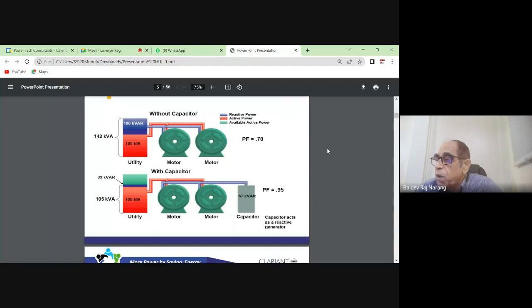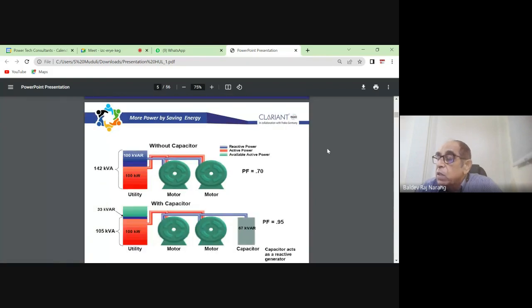So a 100 kilowatt active load will have 100 kVAr of reactive power also. The multiplying factor here is 1. So 100 kilowatt also draws 100 kVAr reactive power. It requires 100 kVAr reactive power to run. The induction machines run by maintaining the electromagnetic field. They need reactive power, and that is coming from the grid.